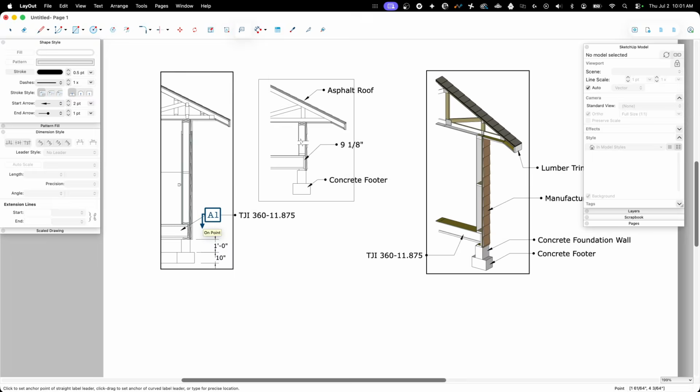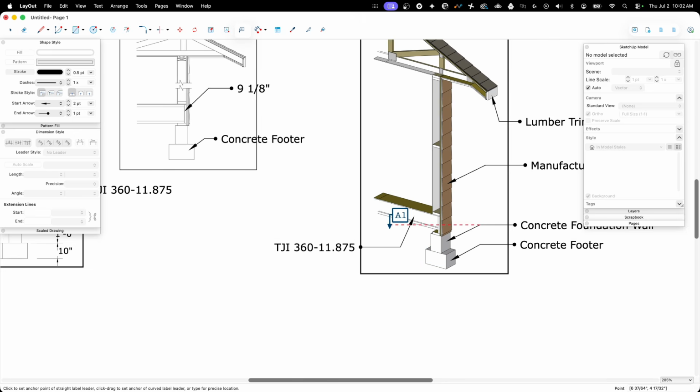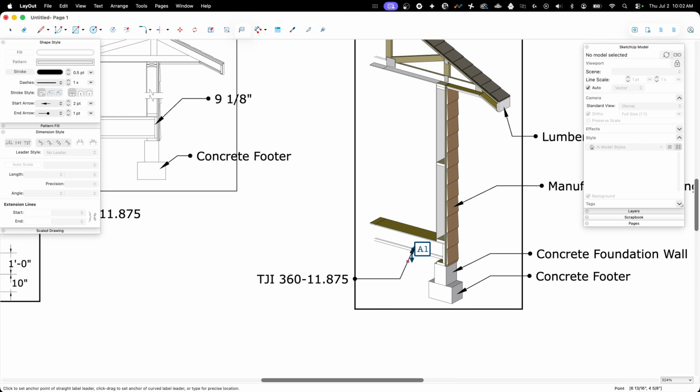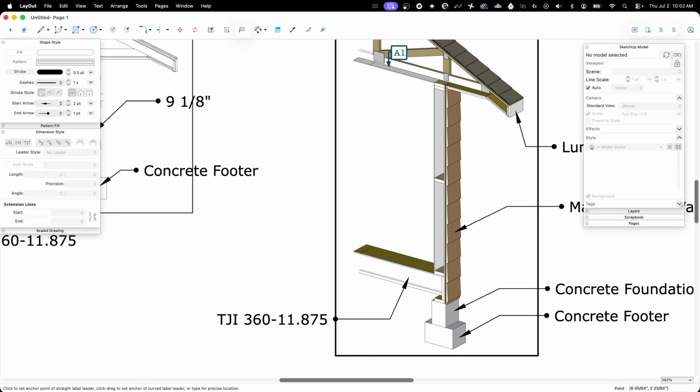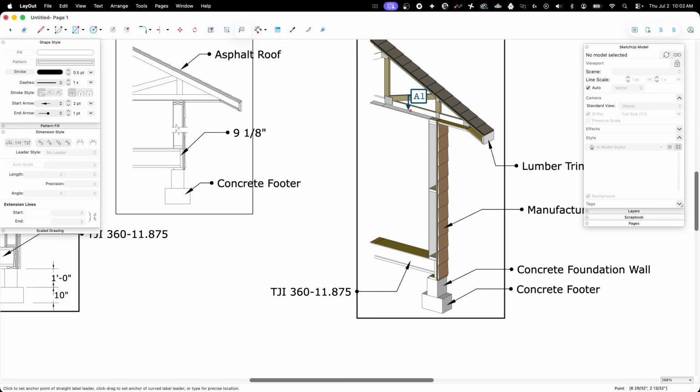So what does this mean? What are the best sections you could possibly put on here? Well, personally, I like the look of this 3D section. There's a little cleanup I'd want to do. I want to go back and probably find out why are my colors not showing up in here. Oh, because I have white set as my section fill color. That's why it's all showing up as white. So I may want to just generate this all in white or make sure that my colors are going to come in properly. So I do a little bit more work to fine tune this so it comes in perfect.